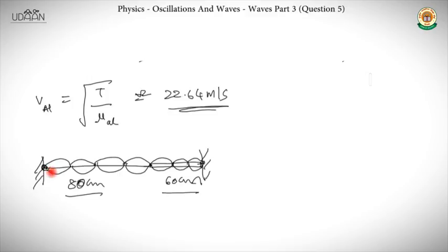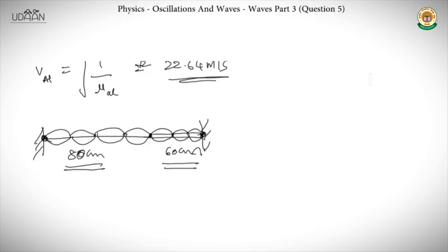satisfy the boundary conditions. That is, the displacement at both the ends is 0, and in the question it is given that even at the intersection the displacement is 0. So based on that, the highest common factor technique is used in this problem. We use the highest common factor technique because it takes into account the fact that harmonics have to be complete in both the parts, and the highest common factor just happens to be a mathematical expression that summarizes that.